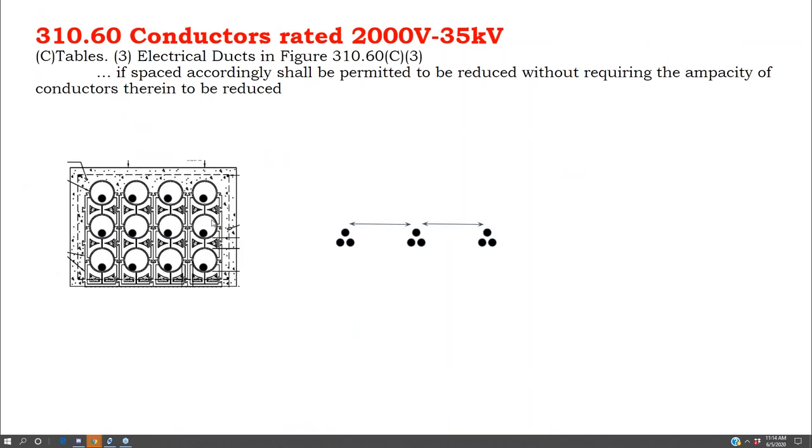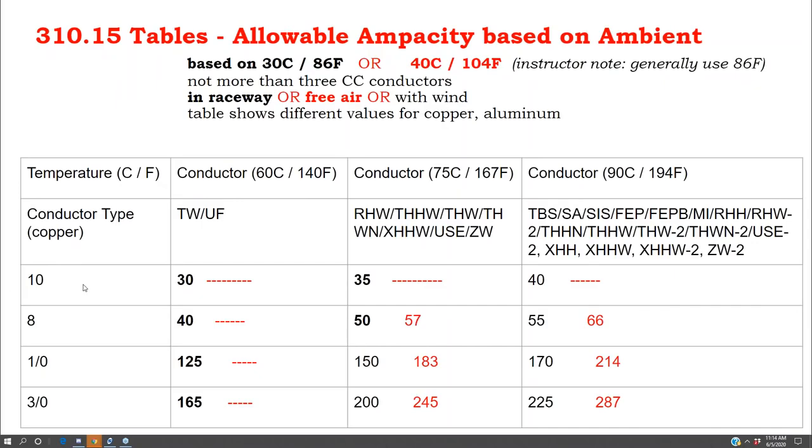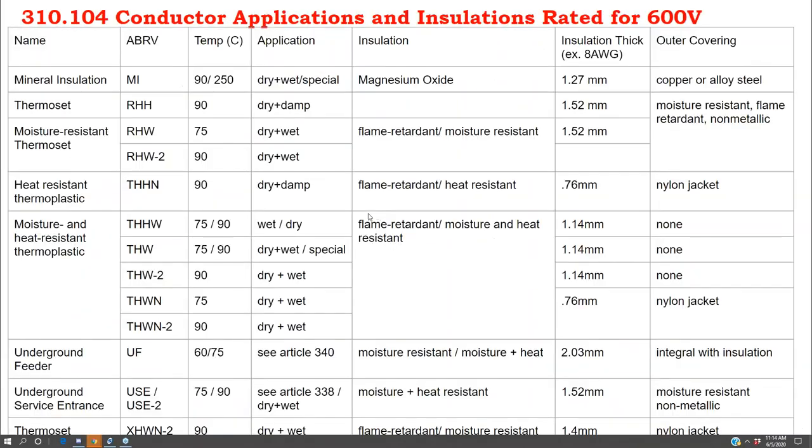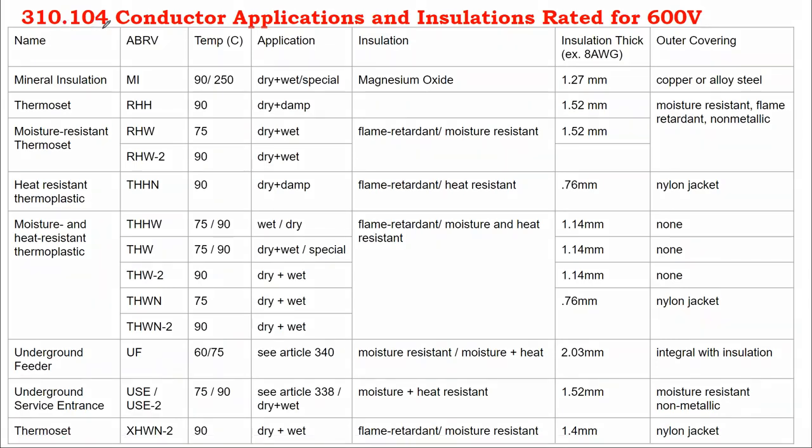Here we go. We talked about this yesterday, that even when you're throwing cables into a trench, you have to space them out in order to avoid them being considered to be bundled together for heat dissipation. Going the wrong way. There we go. So now we get to a section that defines what all of those table wiring acronyms mean.